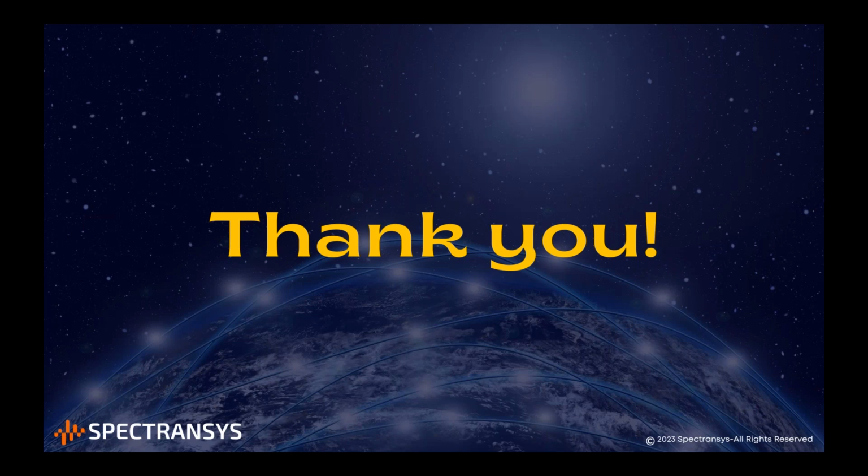But what I'm trying to say is there are some chronic problems, especially design-related problems, which don't disappear. Sometimes they exist from your commissioning stage, or they may start after 2 or 3 years, and then your conventional analysis will not give you a solution. For example, you thought it was an alignment problem, you realign the machine, and you start the machine, still the vibration problem is there. Or you think it is a balance problem, you go on doing the balancing, but it doesn't respond. That's where you should think that it is a problem to be escalated to a higher level.